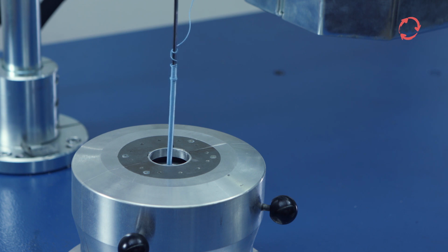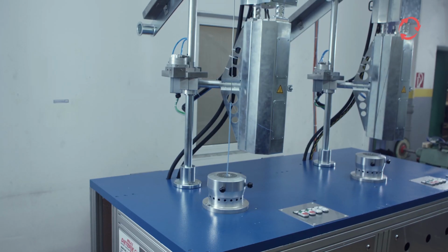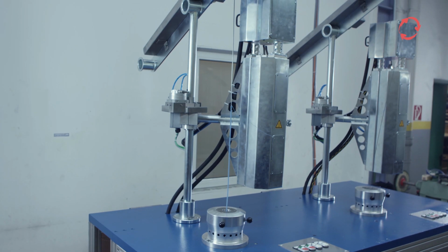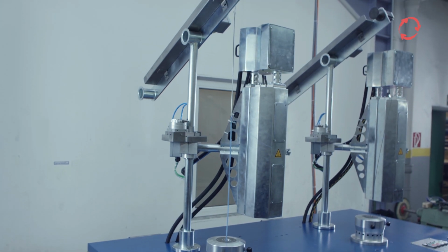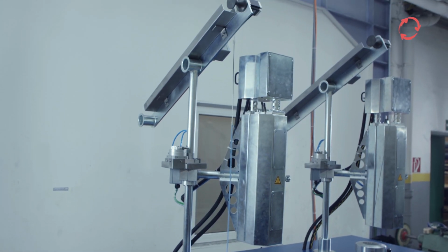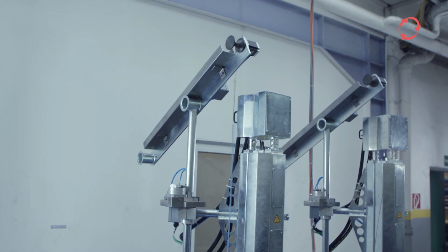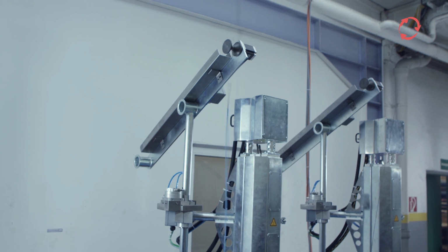During the startup phase, the wound spirals, as needed according to spiral type, must be lightly pushed up onto the mandrel by hand, to avoid tangling and a resulting tear in the thread. Then the spiral must move upward on the mandrel by itself. If this is not the case, then the process parameter is not correct.